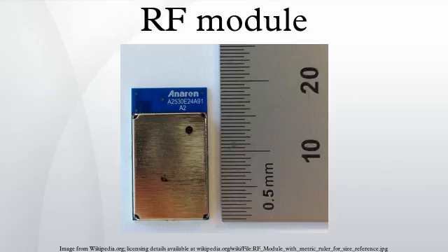Receiver modules. An RF receiver module receives the modulated RF signal, and demodulates it. There are two types of RF receiver modules: super-heterodyne receivers and super-regenerative receivers. Super-regenerative modules are usually low-cost and low-power designs using a series of amplifiers to extract modulated data from a carrier wave. Super-regenerative modules are generally imprecise as their frequency of operation varies considerably with temperature and power supply voltage.